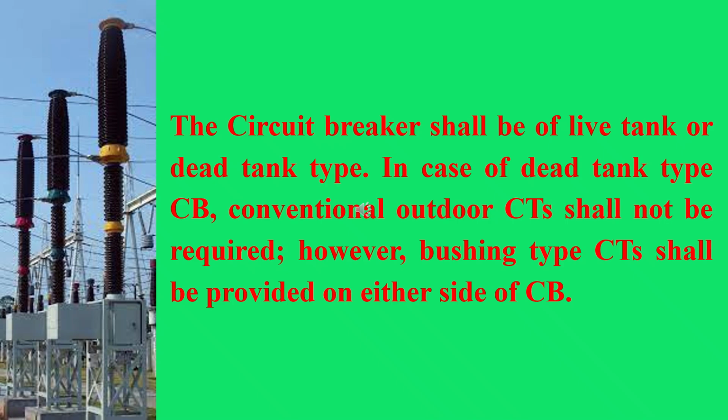The circuit breaker shall be of live tank or dead tank type. In case of dead tank type circuit breaker, conventional outdoor CTs shall not be required. However, bushing type CTs shall be provided on either side of circuit breakers.